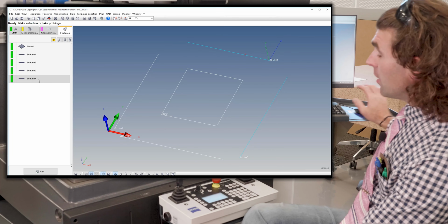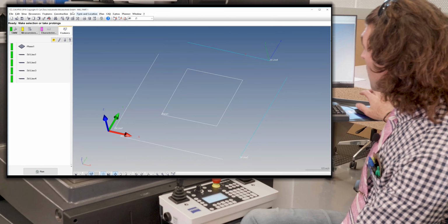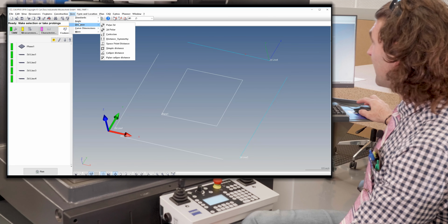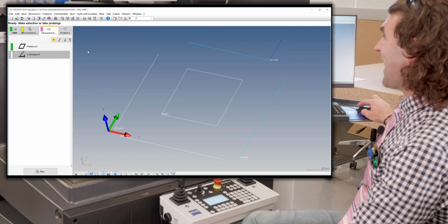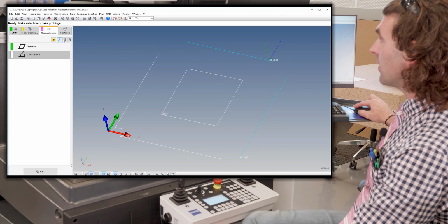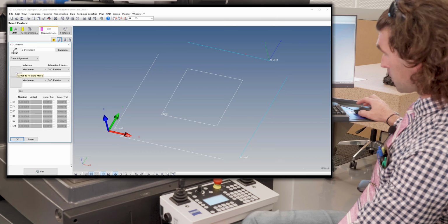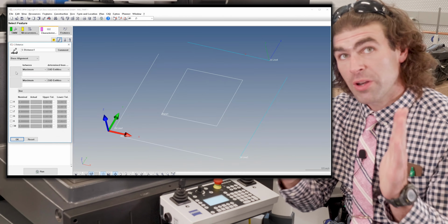We're going to want to measure that 3 inches plus or minus 20 thousandths. What we'll do is go to size, distance, and in this case, we'll use a caliper distance. Okay, so caliper distance, again, we got this gray box. I'll hit the pen tool, and we're going to select the lines we want to measure between.